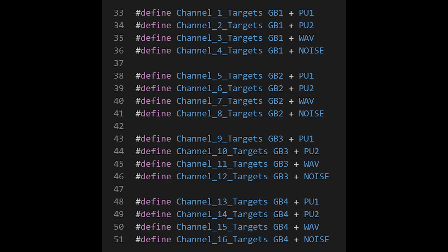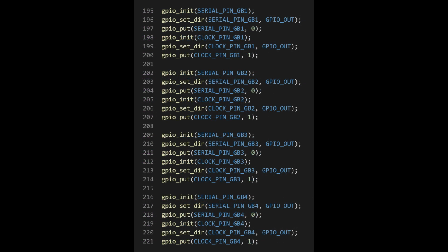Next, we'll need to deal with the actual transmission of our signals. To do so, we'll first have to initiate all 8 output pins that we've previously defined for digital out transmission. Additionally, we'll pull all clock and serial signals of our system to their electrical resting point level. For our serial in pins, this level would sit at a logical low at 0 volts. And for our clock pins, that resting point would sit at a logical high of 3.3 volts.